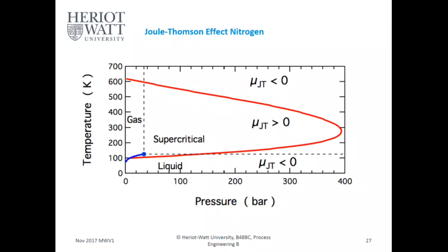A lot of the time in the oil and gas industry, you'll be working in the supercritical phase. For example, you're modeling with Aspen, HYSYS, Pro2, whatever software you use, and you forget that you're in the supercritical phase. You get the data out, you build your pipeline, and you find out you really screwed up because the density you assumed might not be that density. You might be 20-30% out. You just spent 100,000, 200,000 per compressor, and you have 20 compressors. After getting fired, you're going to jail for a long time. So pay attention to that.